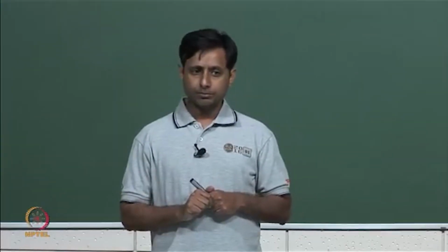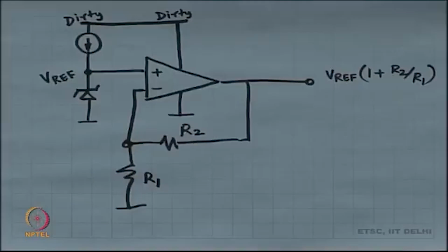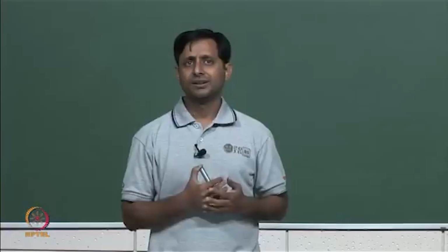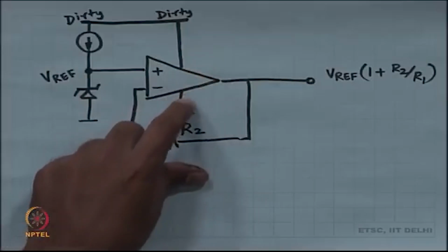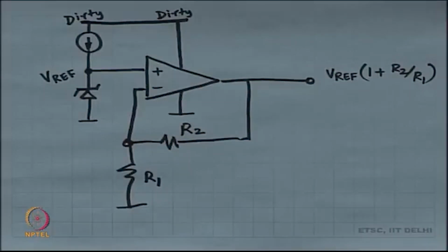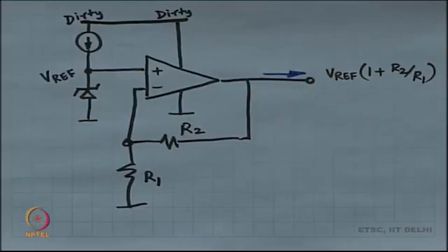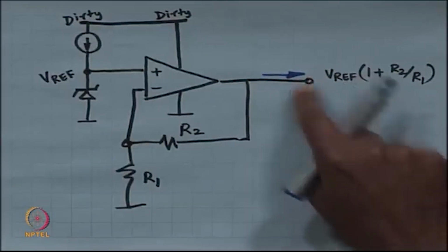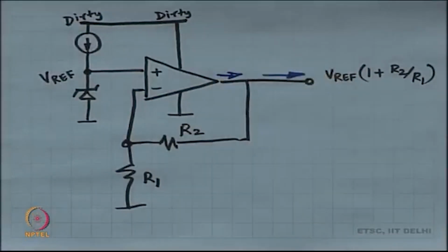There are two things over here. One is the loop gain, the closed loop gain of this circuit. The other is the amount of power that you can push. This op amp has to now be able to drive all the power demanded by the actual analog circuit. So, all of that current has to come out through the op amp. Generally, that becomes a big bottleneck.